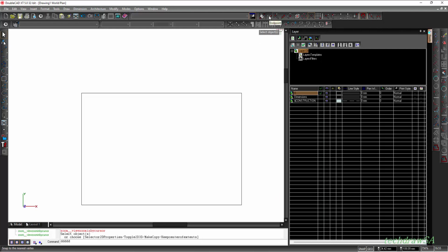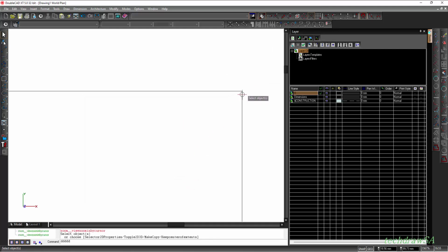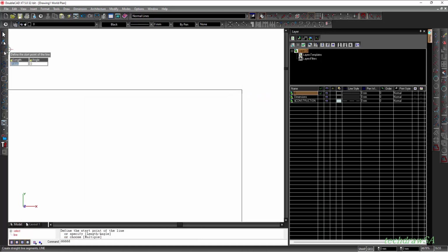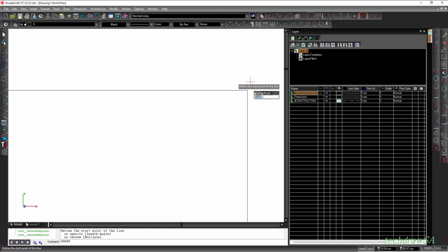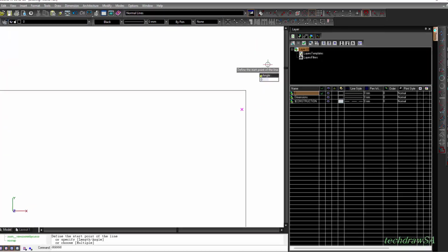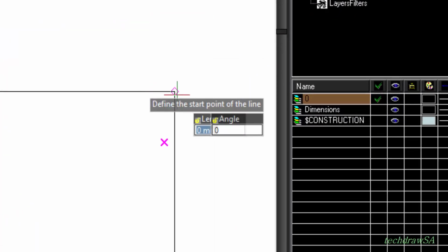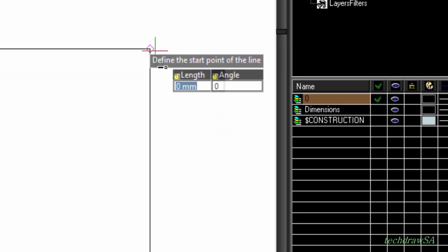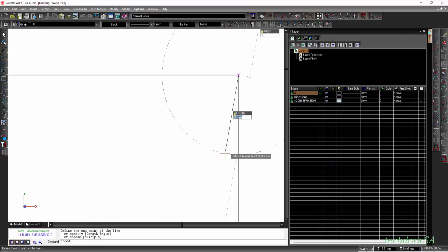So I have my vertex or endpoint selected, I've got my magnetic point there, and I've got the intersection. Those are all active, so that's what I want to use in my snaps. If I now were to select any tool here on the far left, and I select the line tool for instance, and I want to select that specific point over there, I have this no snaps on, and that's why you don't see that little diamond that usually pops up. So you just unselect that, make sure the endpoint is active, and now if I zoom in, you will see there's a little diamond shape there, and now I've selected that.